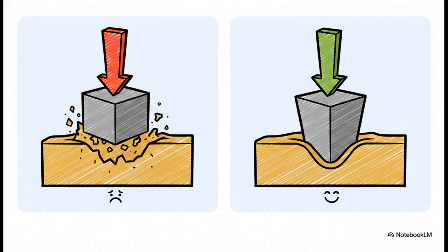Now I want you to imagine trying to pull this oversized pattern out of hard-packed sand. If the sides are perfectly vertical, meaning no draft, those sides are going to scrape all the way up, dragging and tearing the sand walls, completely ruining the mold. It's exactly like trying to pull a perfectly square, straight block out of tightly packed dirt. The suction and friction just fight you the whole way. But if we apply a draft allowance, which means we taper the vertical surfaces slightly, kind of like a wedge, the moment you lift it even a single millimeter, the entire pattern separates from the sand walls instantly. The mold stays perfectly protected.